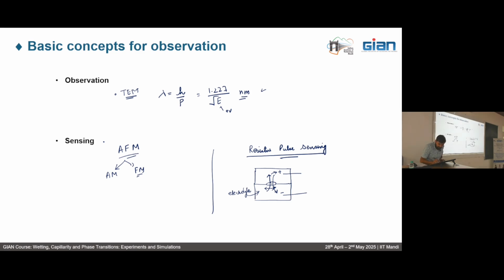So when the bubble nucleates in the center of this nanopore, it blocks the channel. There is a decrease in the flow of ions when the bubble is nucleated there, which means that if we capture the signal of I versus t, where I is current and t is time, we can see that usually the signal would be high, but when the bubble is nucleated, the signal drops. And then when the bubble collapses, it again reaches its normal position. And through this we can sense whether we have bubbles there or not.